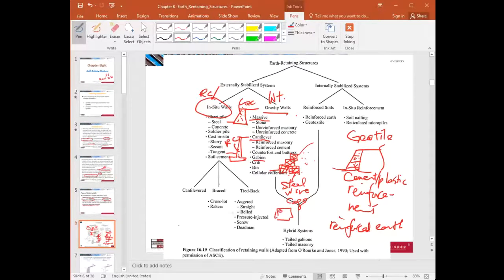So you have the rocks here, and that's your steel wire cage. So you have a box made up of steel wires, and inside the cage you put all the pieces of rock. By stacking individual steel wire cages, you will have a very heavy gravity wall. So that is the Gabion.